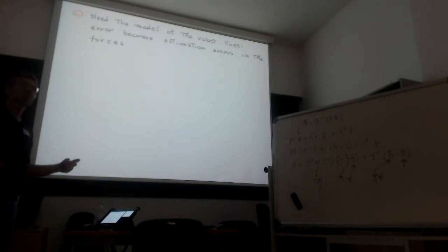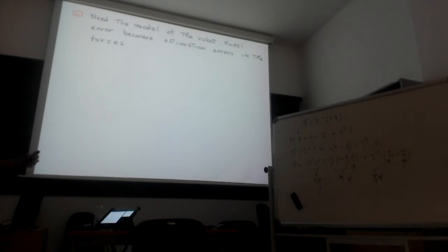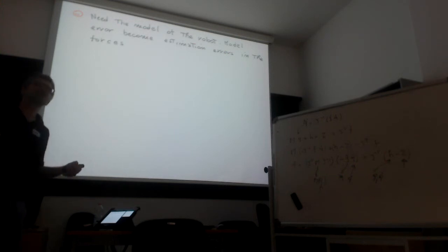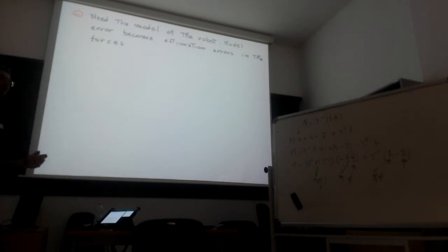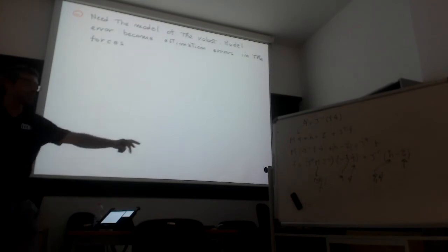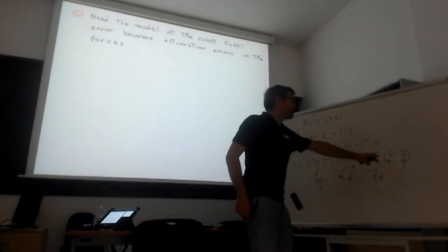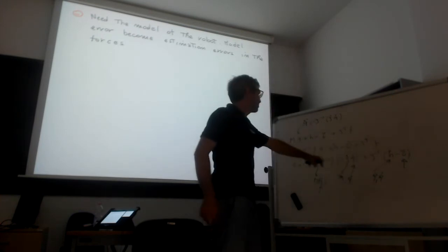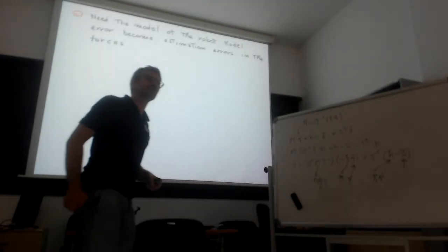What we see whenever we have a torque offset and the robot is in the air and we estimate the forces this way, we see that there are some residual contact forces that are fake, that are due to the torque offset, because the torque should be just equal to the gravity, but actually there is an offset, so it shows a force.